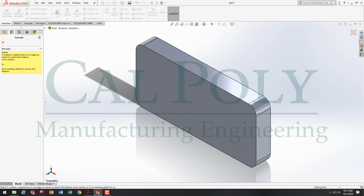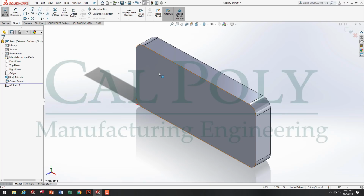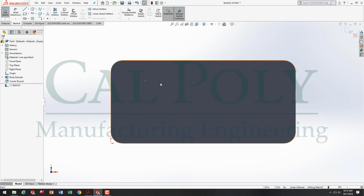Next, I have to select the plane in which to cut out on. So I'm going to select the front face of the model. Now, in order to orient the view normal to my face, I hit spacebar and the normal to button. This makes the 2D sketch become normal to my view.